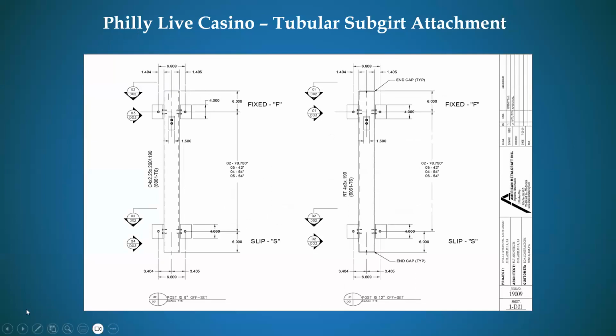And in some cases, the perforated panels themselves cantilever off the bottom of the support system nearly 40 inches. So when you think, wow, that's an awful lot of backup for a perforated system, those are the reasons: big cantilevers and off the wall by over a foot.